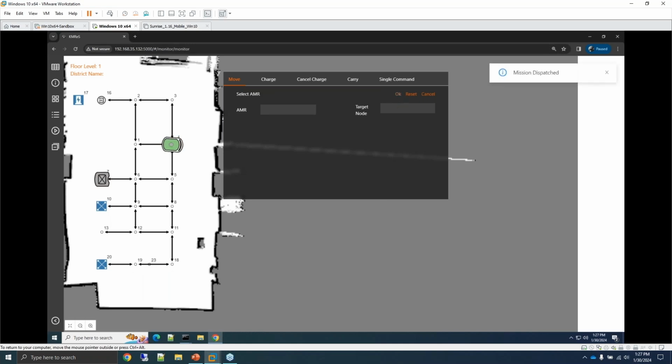This will create a mission for the robot, and this robot would then be commanded to move down there. I have a rest node, that parking node that it came from, already set up. So after the mission is done executing, after a few seconds of inactivity, no new missions have arrived to the robot to tell it to do something else. At that point where this time frame expires, the robot will be instructed to go back to the park position.